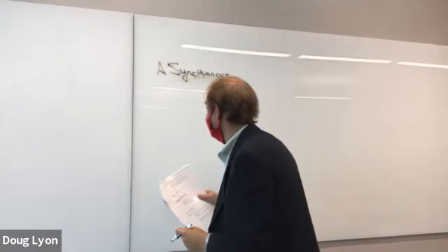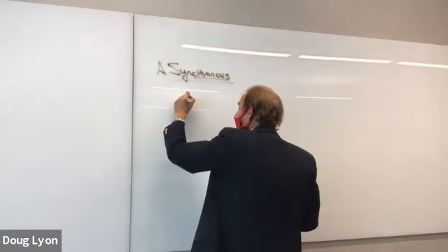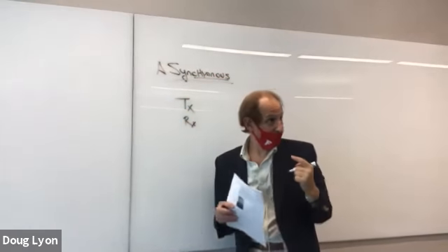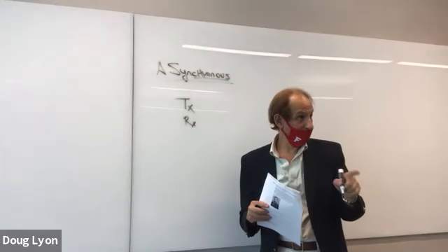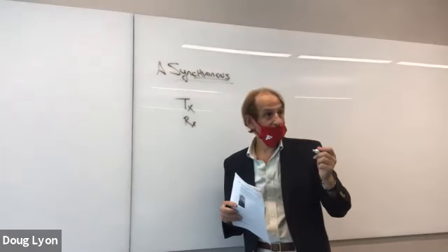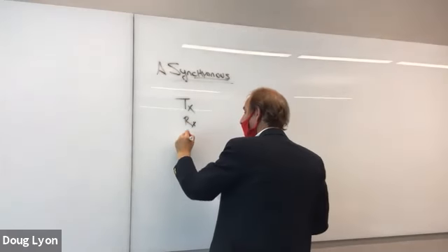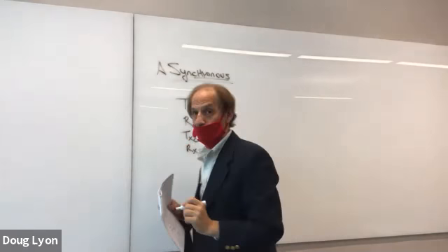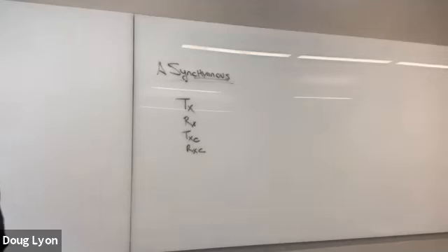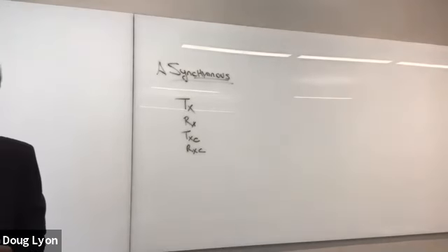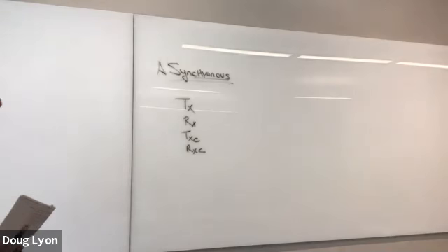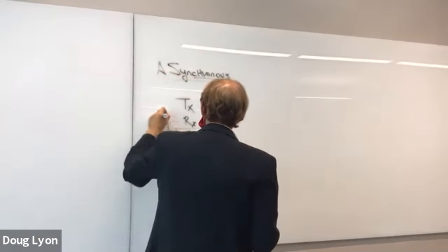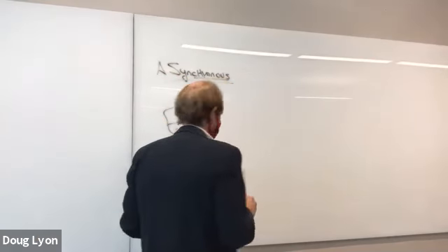When you have a serial communication protocol, you can have a transmit line and a receive line. The transmit line will transmit binary data, and the receive line will receive it. And that's clear. But if you want it to be synchronous, then you're going to have a transmit clock and a receive clock. If you have synchronicity in those clock signals, you can run at much higher speeds. But an asynchronous system will try to embed the clock signals directly into the transmit and receive lines.